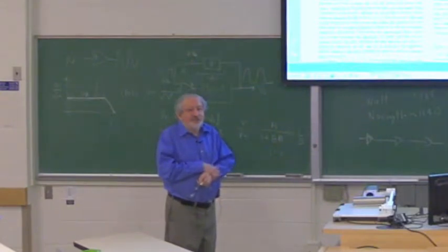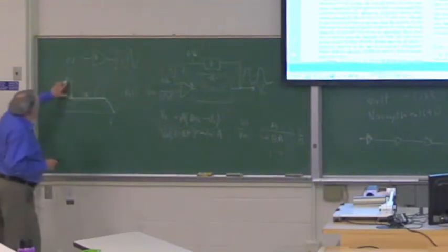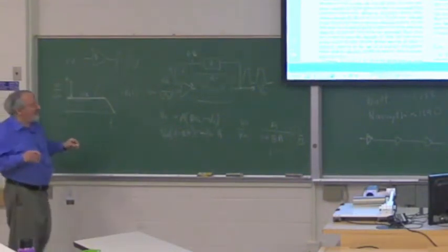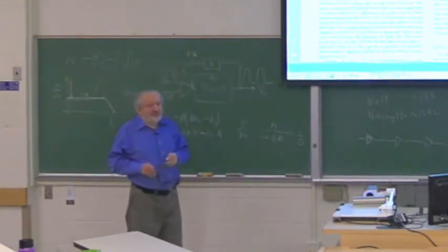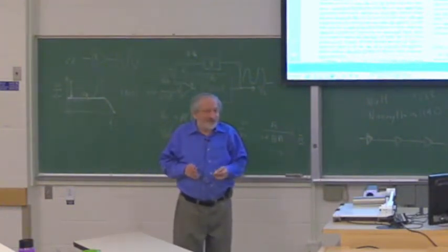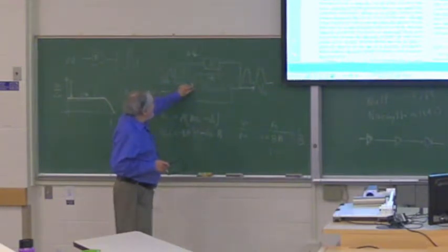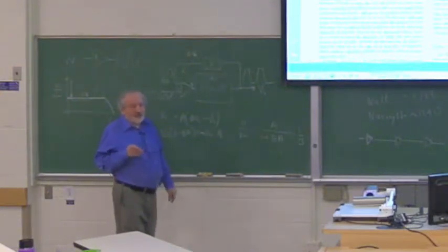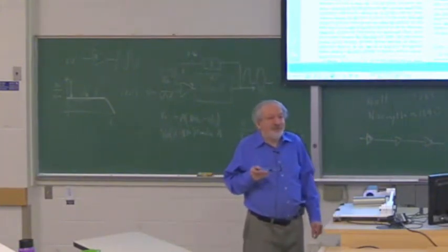It will reduce the distortion by basically an amount proportional to the excess gain. So if you have an amplifier which has a gain of 100 and you close the loop and give it a gain of 50, there is not that much excess gain to fight distortion and so on. But if you have an amplifier with a gain of 1,000,000 and you use it at a gain of 100, the amplifier has a lot of gain to detect any small difference between these two and fight it. Okay? For example, if you look at an op-amp, the open loop gain of an op-amp is typically 1,000,000 to 100,000,000.